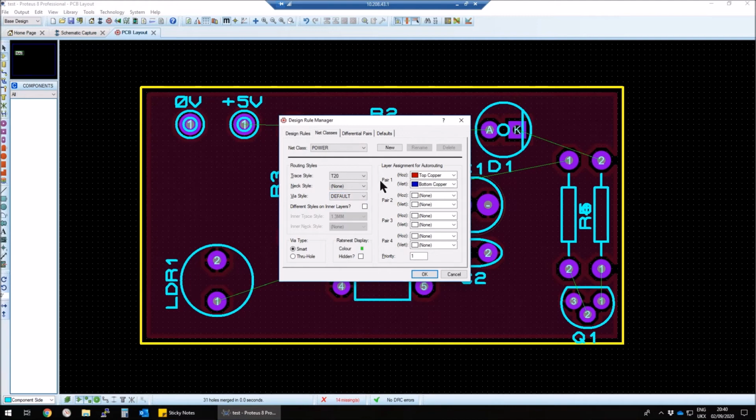If each track is made smaller, then more tracks will fit in a given board area. The thickness of the power tracks will also depend on factors like how much current they're expected to carry. Higher currents will require a thicker track. A necking thickness can also be specified.